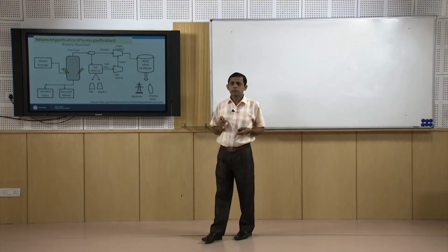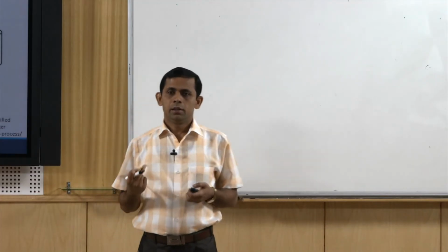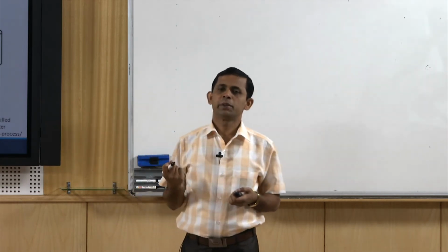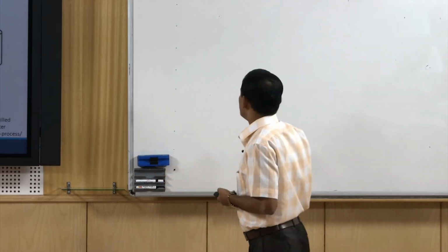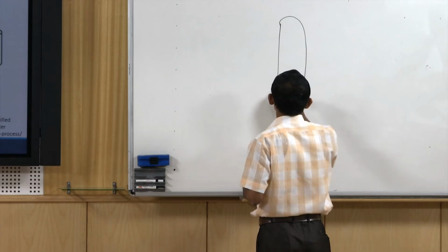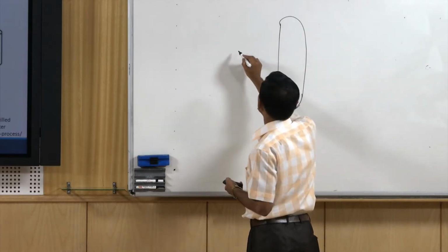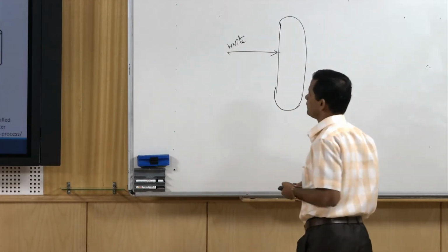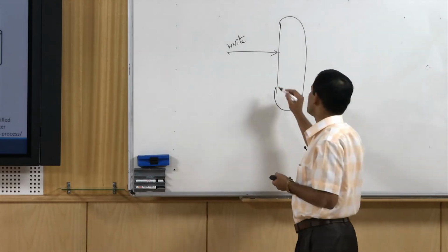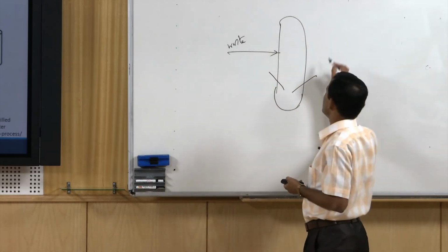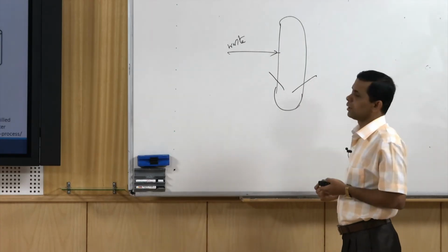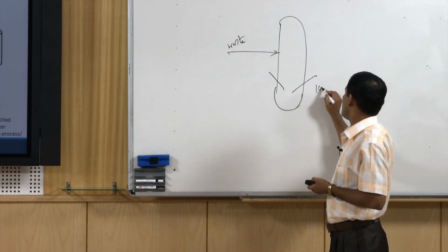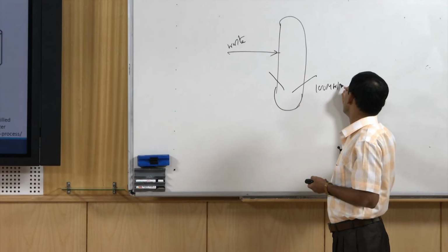So, the main change will be with the pretreatment. In case of entrained bed gasifier, pretreatment is essential, but in case of plasma gasifier no pretreatment is required. So, the waste can be directly charged to the gasifier without any pretreatment. Another is, we do not need to supply oxygen or air, in spite of that we will give external source very high voltage.